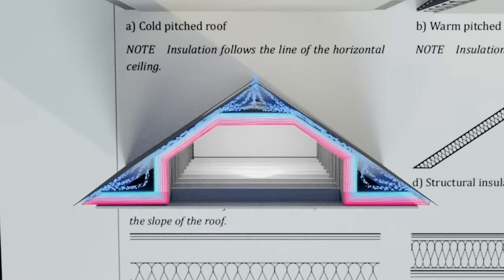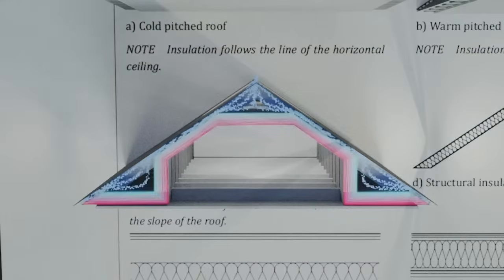Another potential issue to consider is the continuity of the insulation layer and the potential for cold spots to form internally. At such locations, moisture vapour can condense internally, causing localised surface condensation and, in extreme cases, mould growth. Similarly, air movement through the fabric of the roof can transport moisture vapour into colder areas, where it can form condensation. Again, this highlights the interlinked nature of heat, air and moisture control in buildings.